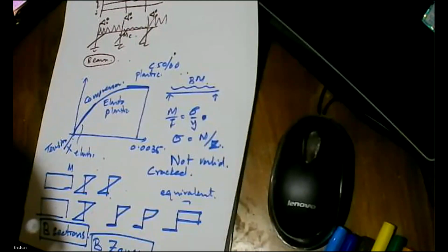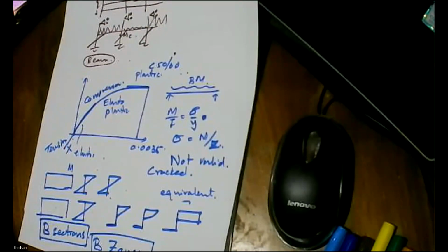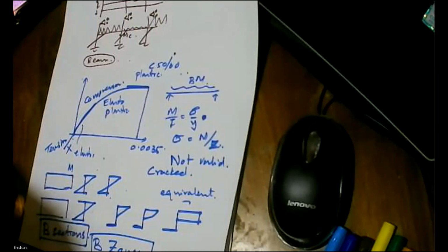Then to allow for that, we have to ensure that the pile has shaft capacity. For the shaft capacity, we said, instead of using 30 megapascal cube strength concrete, let's use 40 megapascal cube strength concrete. Even if that is not sufficient, let's go for 45 megapascal cube strength concrete. It's up to us to make adjustments.